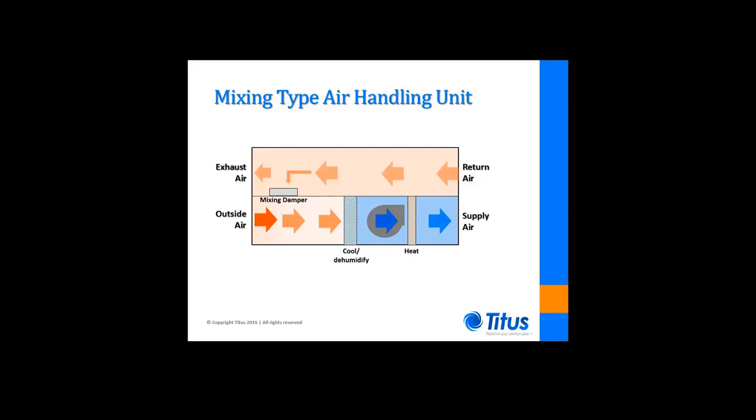classroom. An effective way of providing the necessary reheat is to provide a heat pipe or runaround coil to transfer heat from the air mixture before it is cooled and dehumidified to reheat the air leaving the coil. Titus also offers the displacement terminal that combines all of the aforementioned displacement advantages with energy-efficient chill beam technology.